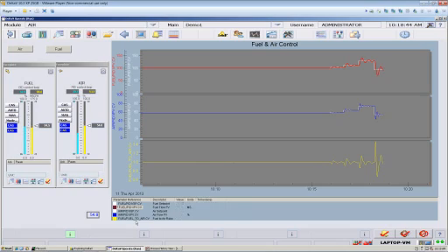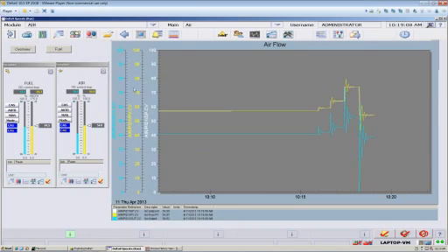I'm showing that with one of the major popular alternatives to Lambda tuning, we have significant overshoot, no coordination of responses, and the bigger our need is, the worse our problems are. We can do better. So let's start with looking at the air loop and how we tune that first. Just going to switch to a little bit different chart here. This is that same air loop. You can see the overshoots we had during my last demonstration.